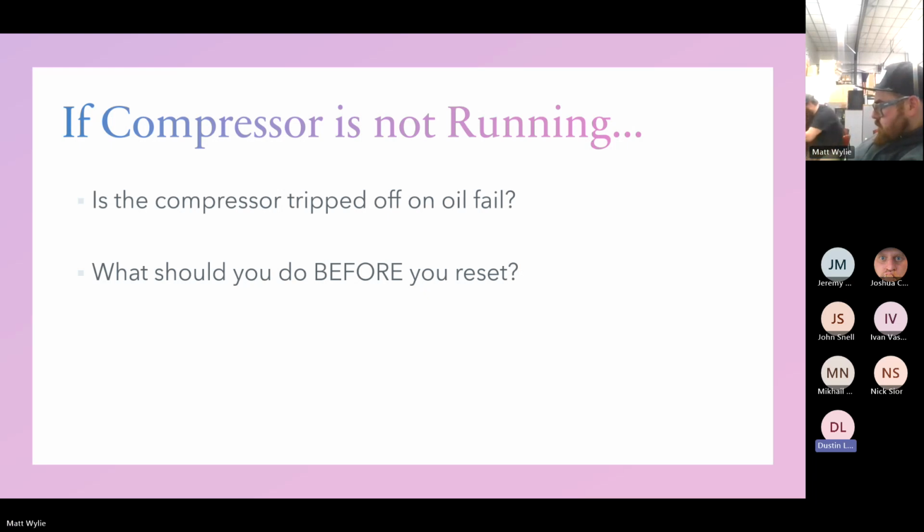If you keep your control voltage on and you walk over and shut off your breaker to compressor 1, but the computer is calling for compressor 1, if you leave it that way after 2 minutes, your compressor will trip on oil fill. Even though there's no power going to the actual motor itself, it tells it it's supposed to be on, but your oil pressure is not there, and it's still going to require a manual reset of your pressure control or your oil fill control.